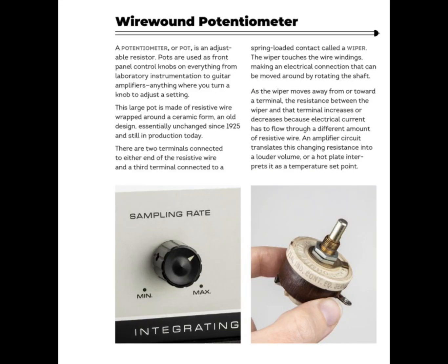Now, the second one is the wire-wound potentiometer. A wire-wound potentiometer comprises several rounds of wire wound around a shaft of non-conducting material. The turns of the coil are bonded together by an adhesive. In this case, the slider connected to the body whose displacement is to be measured moves on the potentiometer track, and it makes contact with successive turns of the coil.